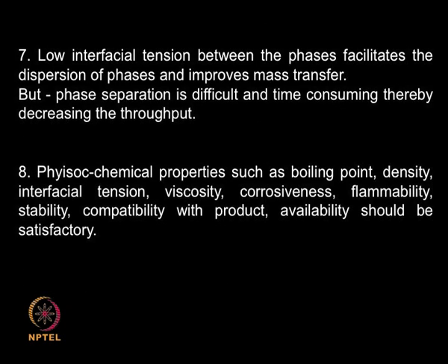If you have very low interfacial tension between the phases, then dispersion of the phases is good and it also improves the mass transfer. But then if you have low interfacial tension, the phase separation becomes difficult. The phase separation takes much longer time, so the separation will be taking a very long time, and hence your overall throughput also becomes very low.